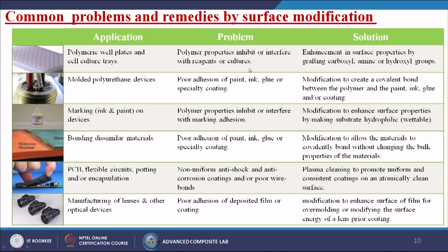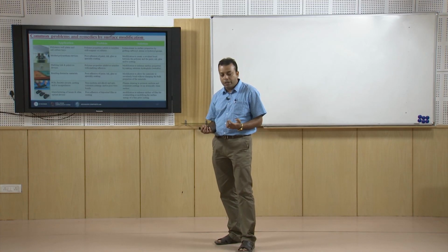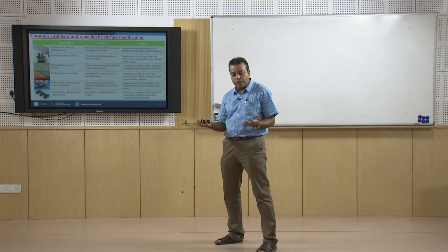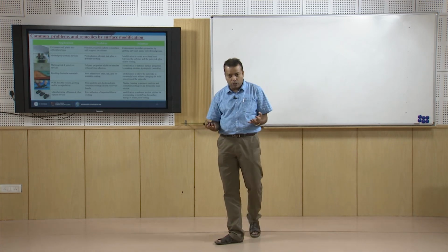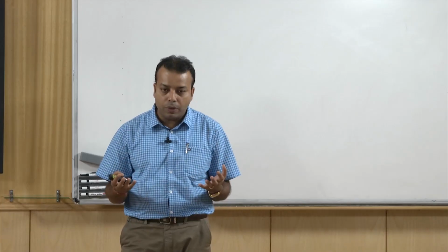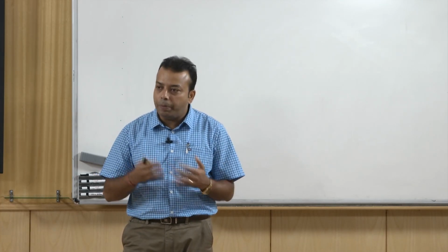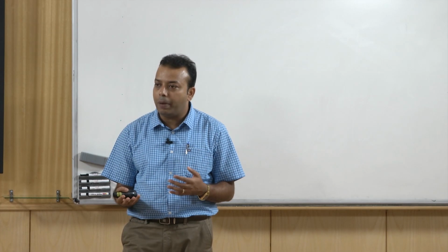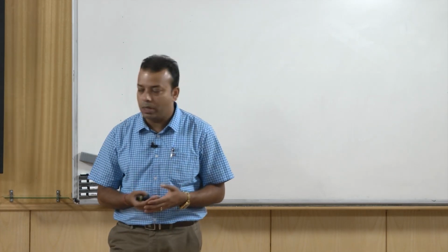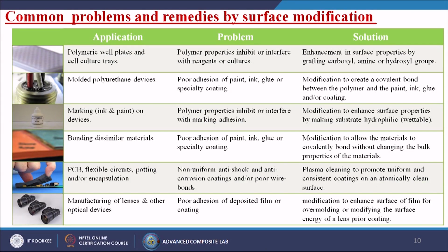Yes, of course, because polymer has a high affinity to react with chemicals, or with any kind of chemical environment. So by doing some modifications we can stop that problem, so that the polymer will not react with any chemical environment or chemicals. The remedy is enhancement of surface properties by grafting carboxyl, amine or hydroxyl groups.